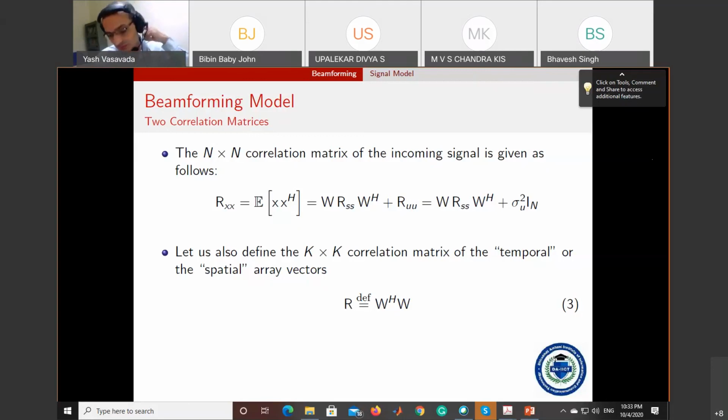I'm saying a specific formula when we are looking at the uniform linear array model, or when we are looking at FIR filters whose impulse responses are DFT vectors. Then the correlation between W F0 and W F1 is given as the summation of a_k squared times e raised to j 2 pi k.